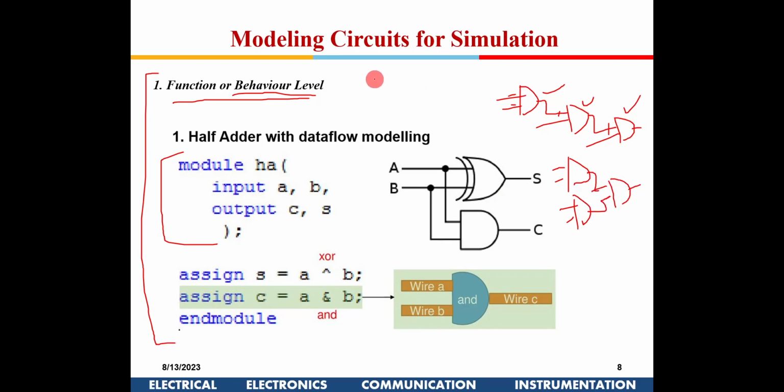In the functional level, I just say y is equal to a b c d in the behavioral model. So the tool can implement it like this, or in another way. If you have set propagation delay as your goal, it might implement it like this. If you have set your goal as low power, it might implement it like this.